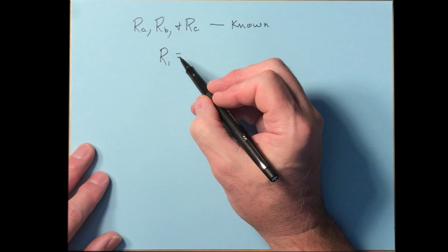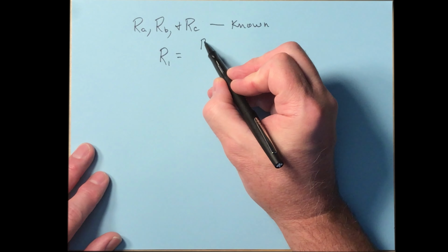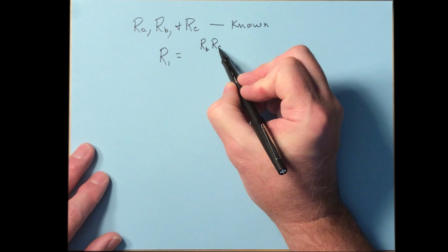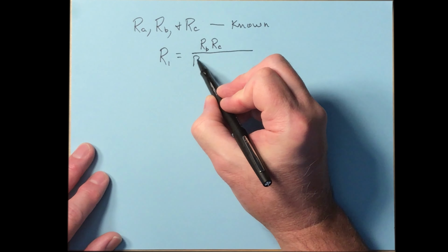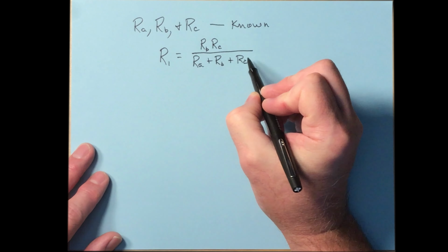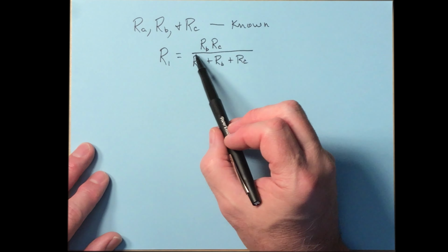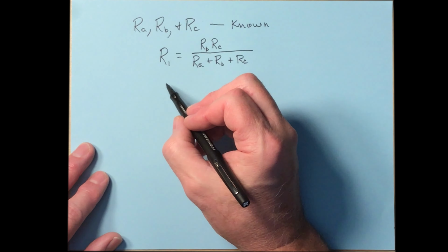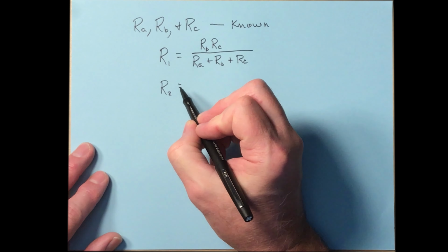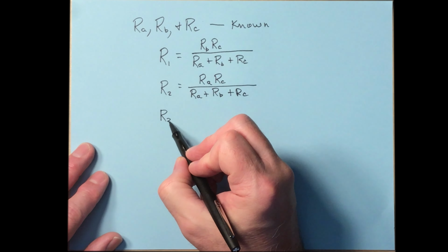You can solve for R1 out of those three equations. And when you do that, you get this: RB times RC over RA plus RB plus RC. So if you solve for R1 out of those three sets of equations, you get this. If you solve for R2, you get this. And if you solve for R3, you get...